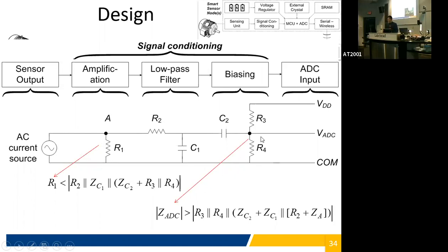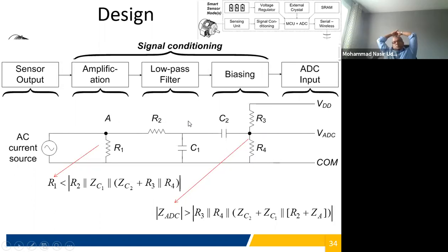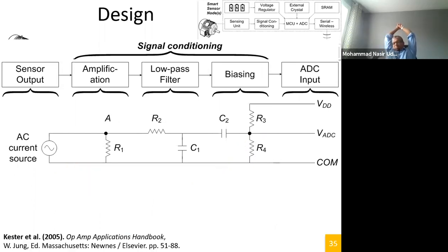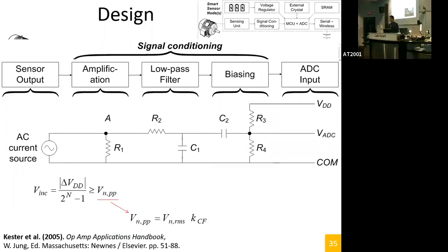Also, the impedance at this point, before the analog to digital converter, has to be within a certain limit of allowable impedances with respect to the rest of the circuit, based on the analog to digital converter's specifications. As for the usable bit range of the analog to digital converter, it is based on noise and bandwidth of the application, as we can see here.